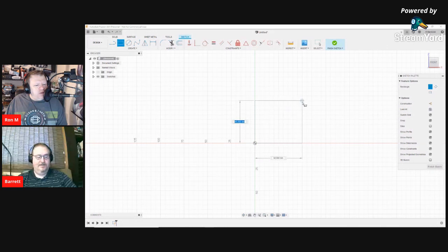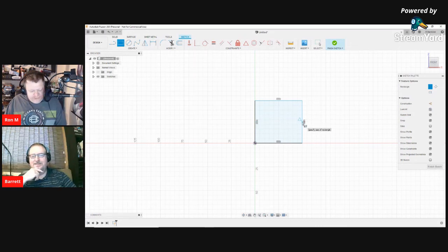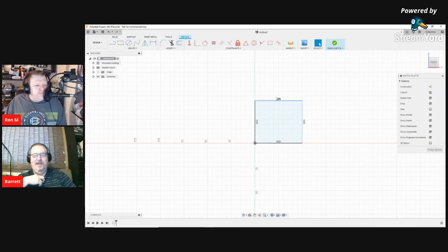Okay, so let's do that then. So if you want to dimension that, do you remember how to do this? I'm trying to remember it, but if you want to tell me how to do that. You're in another rectangle right now, so if you hit escape. Oh, yeah, escape. Sorry. Okay. So now if you hit the D tool, that'll bring up your dimension tool. And you can select the two sides, or if you just select a face, it will give you the dimension.